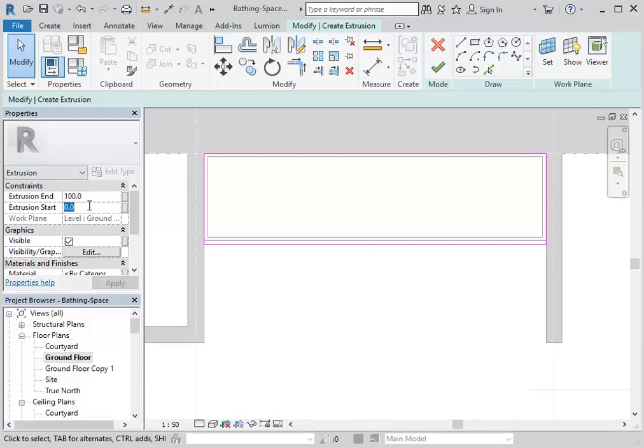So then now looking at the depth, it's going to be starting at 100. So all of the others so far, they've been starting at 0, which means they start at the height of the level you're on, ground floor. Here I'm starting at 100 because I want it to start on the top of that kickboard. And then my end will be the height of the bench minus bench thickness, which is, let's say, 35 mil.